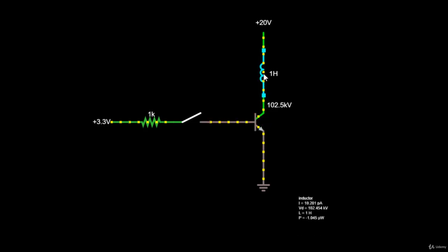So what can we do to protect our transistor so that we can safely turn off the motor? Well, back EMF cannot be prevented, but it can be controlled. In suppressing the back EMF, the objective is to prevent the very high voltages and dissipate the stored energy in a controlled way. There are a number of ways to do this, and we will look at one of the most common methods used. So the most common method is to use a flyback diode in parallel with the inductor.